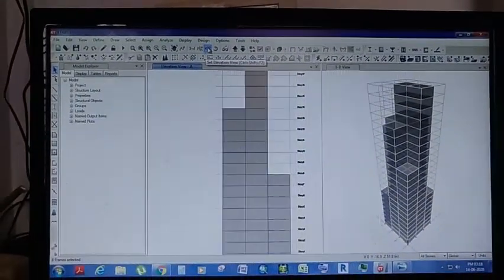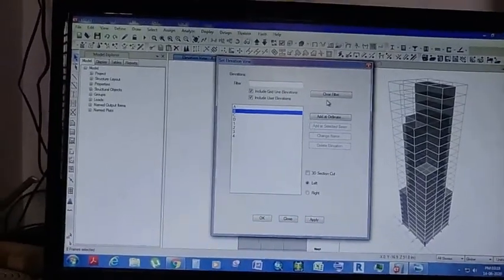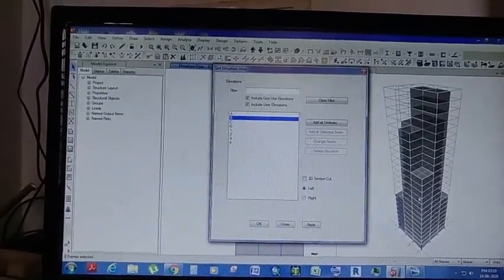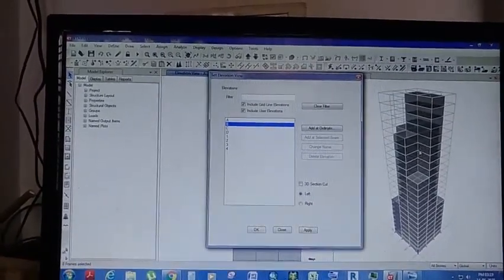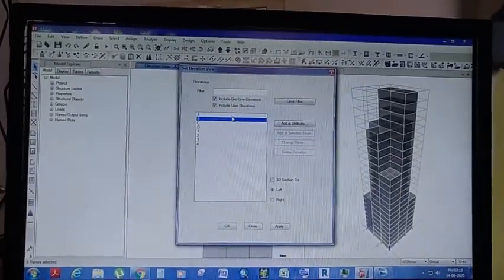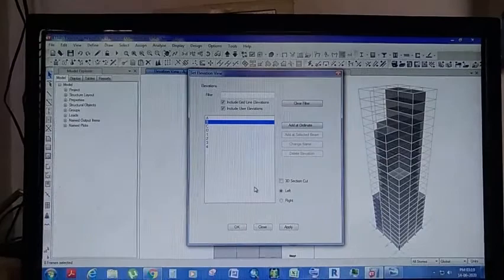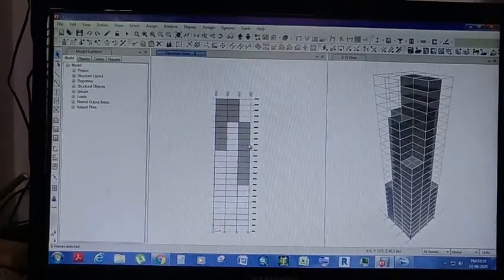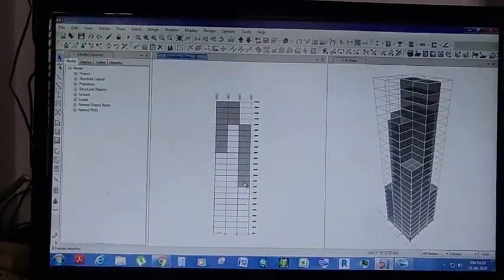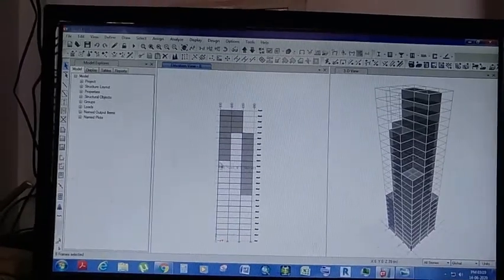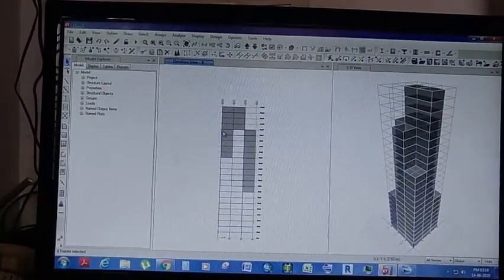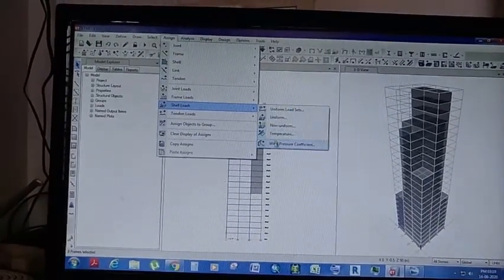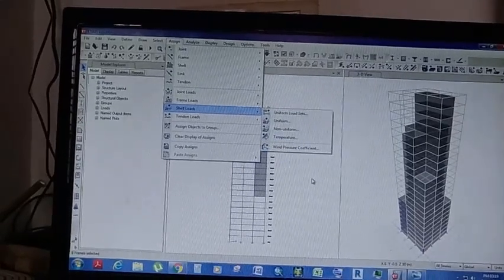Similarly, the load is assigned to the elevation B, as you can see that the wind from this A, the floors here also, the wind is exposed, and selecting the elevation B. These elevations are also selected. This section of the beams of the building are also selected, and the wind coefficient is also assigned to this.